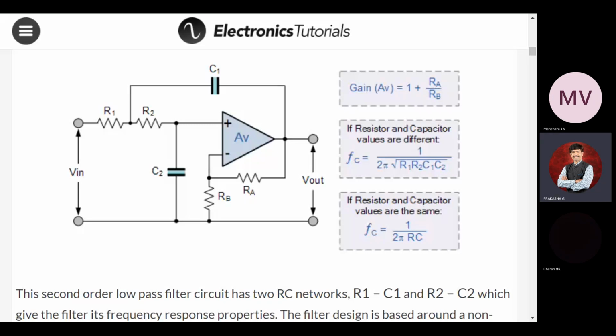That is what was given in your previous waveform, where you can get different cutoff frequencies by selecting different R values. We know the gain of the filter and the actual cutoff frequency of the filter, and based on that we select the R value and C value.